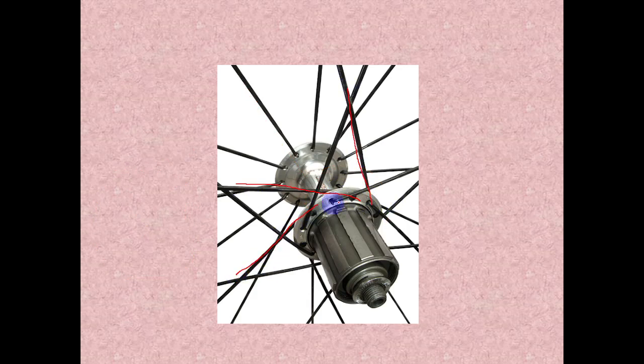When you are moving forward or backward also, alternate spokes will be connected in the opposite direction. So that will take care of the tension. That is the reason all these spokes are connected tangential to this hub. It's not concentric to this hub.